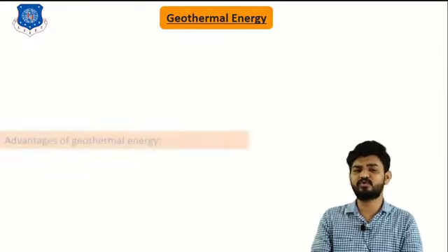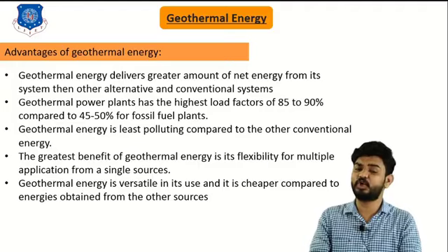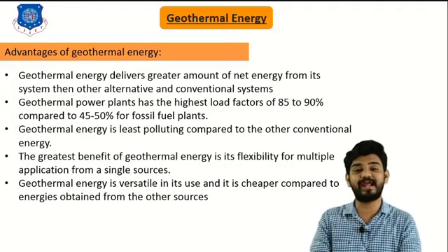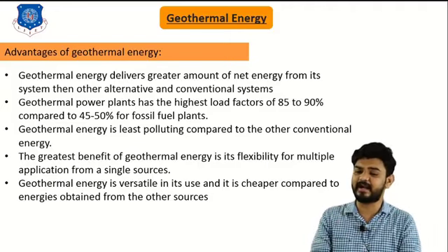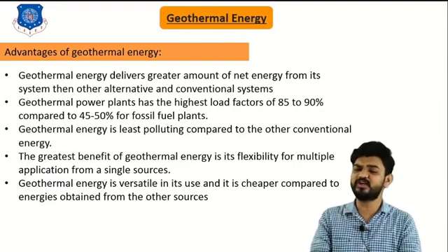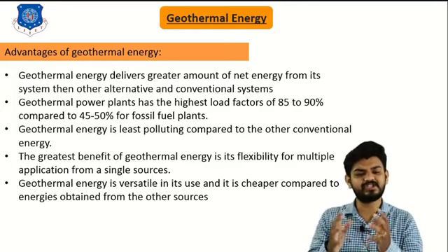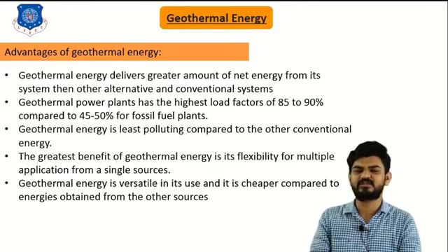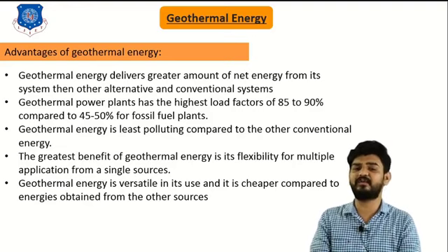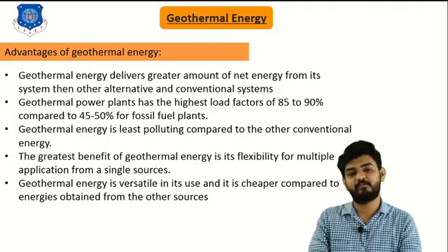So now let's move to the different advantages and disadvantages of this geothermal energy. It is also a very important question from the exam point of view. The geothermal energy delivers a great amount of net energy compared to other non-conventional sources of energy. Well, a geothermal power plant has the highest load factor, around 85 to 90% compared to 40 to 50% for fossil fuel plants. This geothermal energy is least polluting compared to other resources. So we can clearly see that we are not involving any kind of fuel in this geothermal energy, so it is not creating any pollution effect.